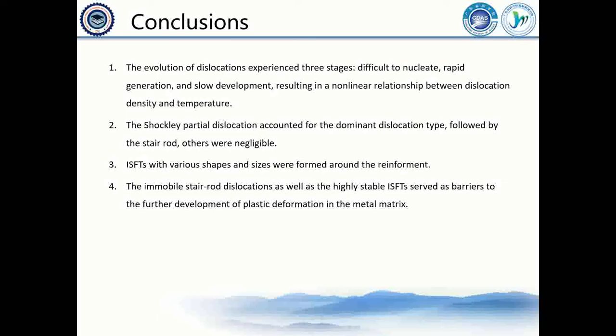And third, the incomplete stacking fault tetrahedron features with various shapes and sizes were found around the reinforcement. Fourth, the immobile stair-rod dislocations as well as the highly stable incomplete stacking fault tetrahedrons serve as a barrier to the further development of plastic deformation in the metal matrix.